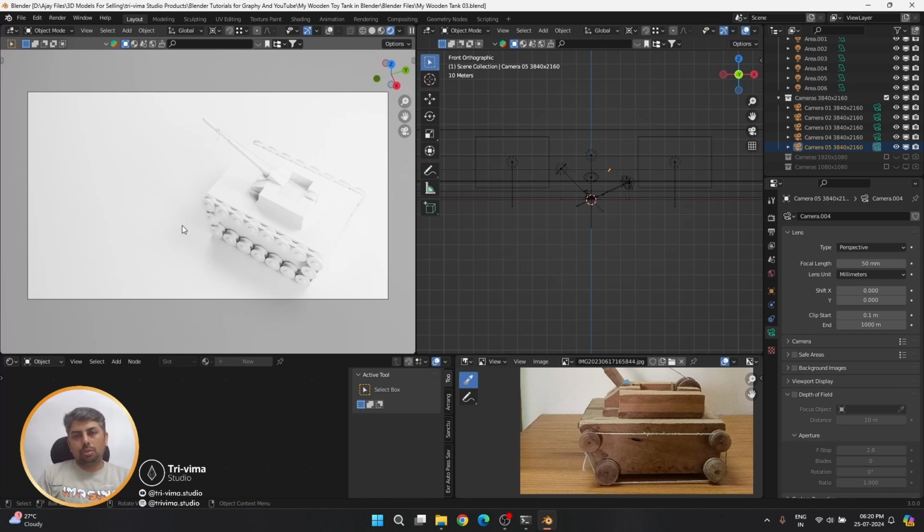But one thing you should monitor very closely: while you light the environment, don't continuously work in the render viewport. I mean render preview. You should do the settings, like changing the size of the light or the angle of it, in live render preview. It will use a full load of memory and it can crash.